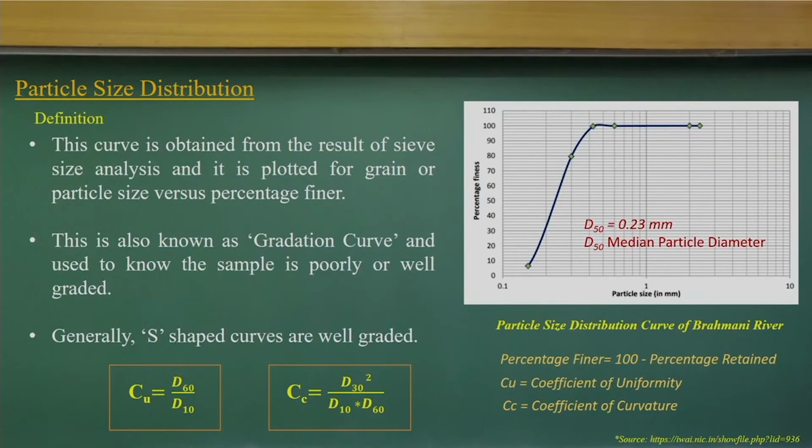Now let's go to very basic things. What do we do? We bring soil bed samples. We go to the field, take samples from the bed level, and bring the soil samples. We should bring enough soil samples to the lab and do a particle size distribution curve, which is a very simple thing. Through sieving analysis, we can find out the particle size distribution curve.